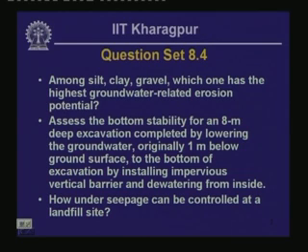So from that point of view, you can see that clay is going to have cohesion, so it is not going to be susceptible to erosion. Gravel is going to be comprised of heavier particles because of the larger grain size, so that is also not going to be erodible as much as silt, which is fine grained, as well as it doesn't have any cohesion as such to prevent the erosional effect of groundwater movement.